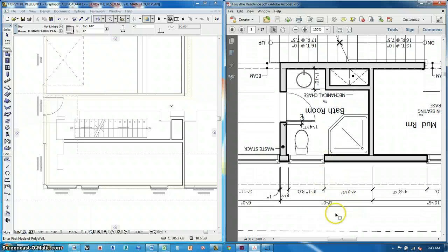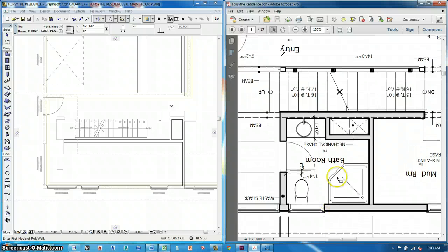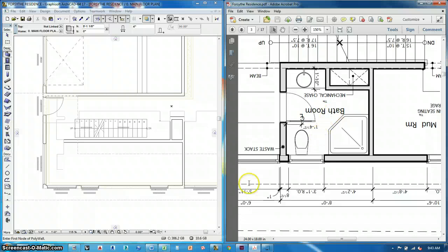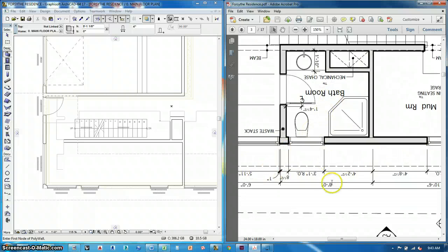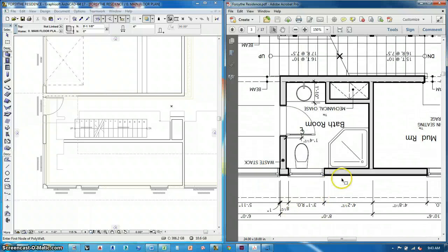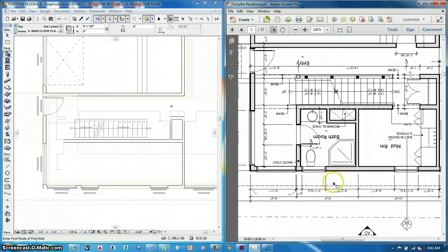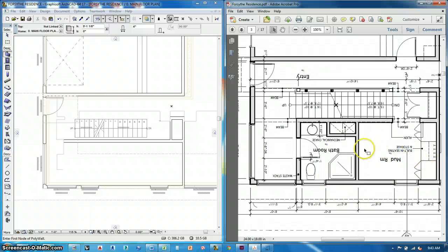Just so you know, this is something you should never do. You should never put interior wall dimensions outside the building and then other interior wall dimensions inside the building. These dimensions should be inside. The exterior dimensions should just dimension the window and door openings. So that's how I'm going to have you guys do this. Sorry, Eric, but you know, I'm going to school everybody on this. All right.